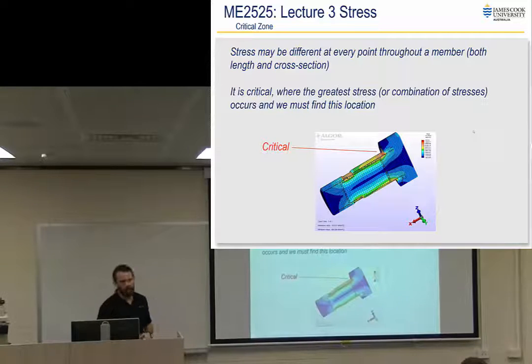And so by working out where the critical zone is, they worked out that this particular force was sufficient to cause that fatigue failure and that it wasn't analysed correctly in the first place. And so that's a lot of the root cause analysis type stuff that I might talk about. Generally happens when something breaks and you go back and look at the design documents and work out what forces they actually used for their calculations, and then you work out what forces something's actually operating at.